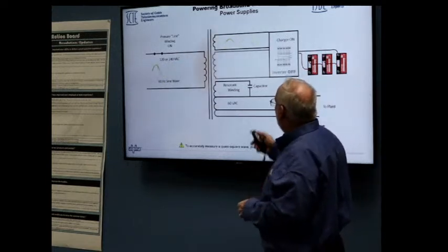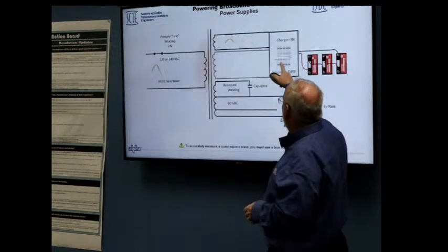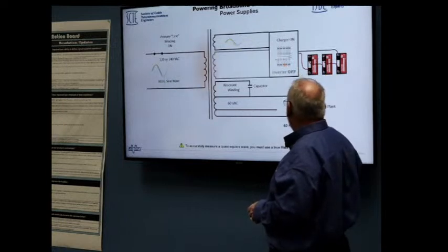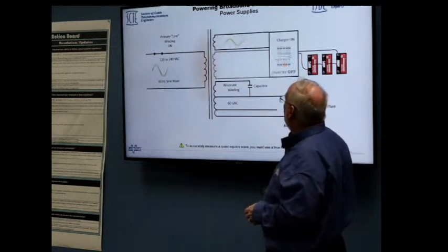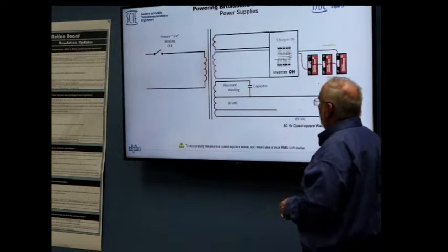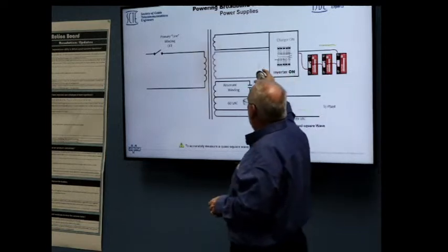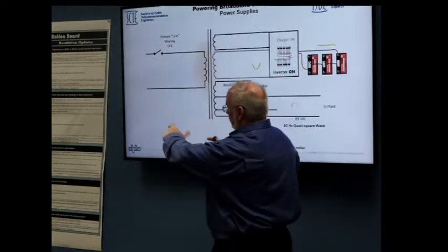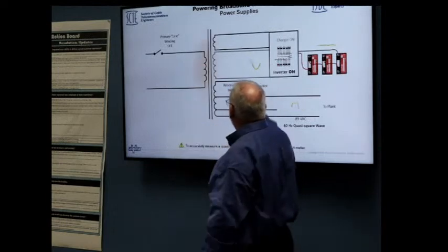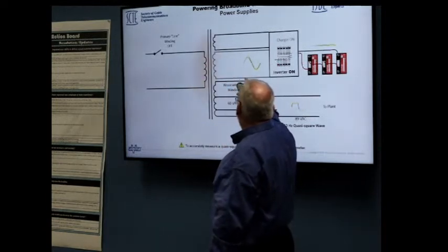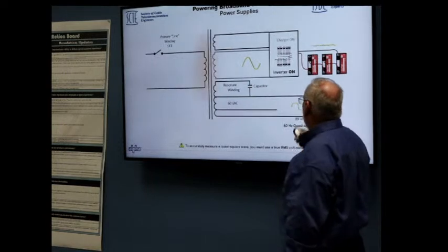And again, looking here, power's going through, charger's on, batteries are getting charged, plant's running, normal operation mode. In standby mode, DC goes back out, it goes through, this H-bridge actually kind of sends it back through. Should be a sinusoidal wave, should be trapezoidal, but it comes out like this.